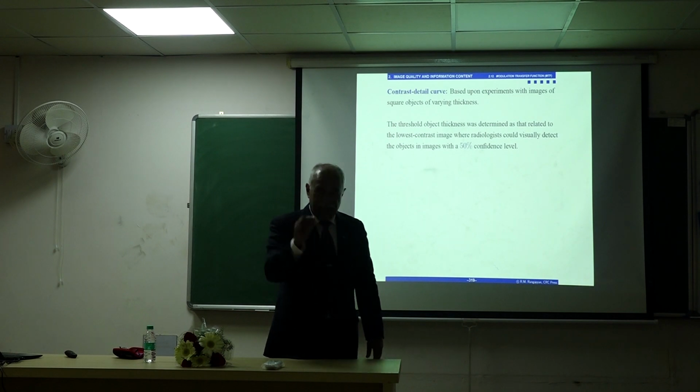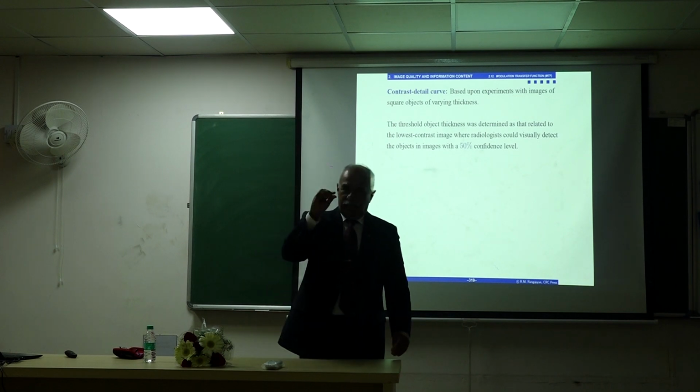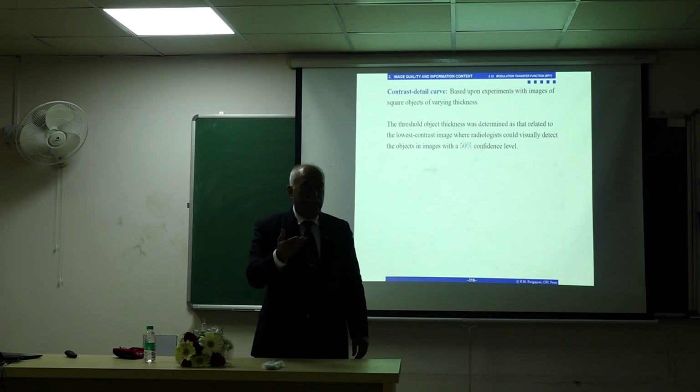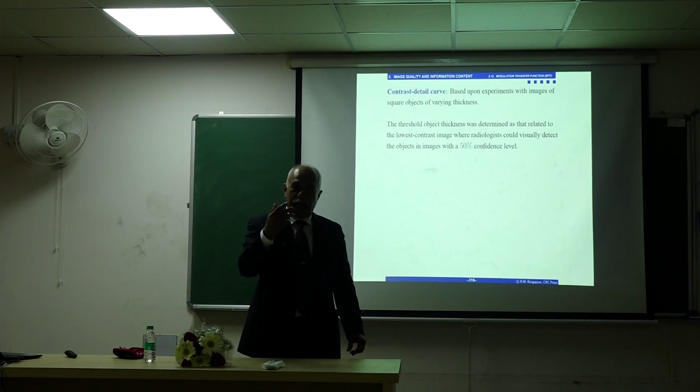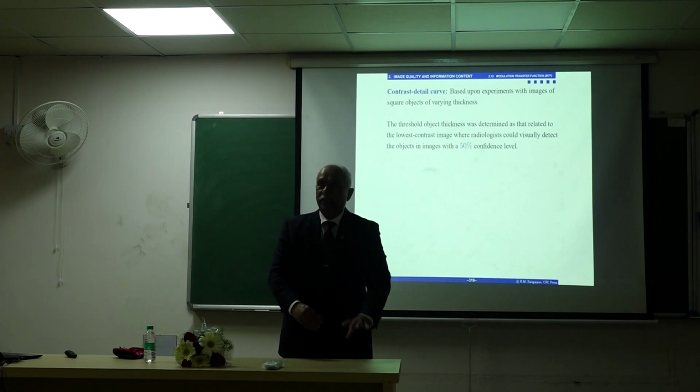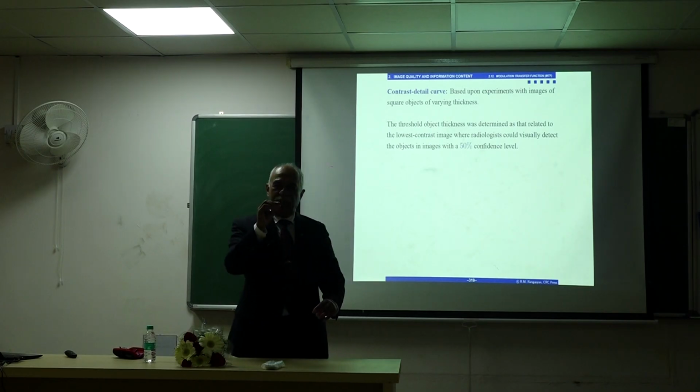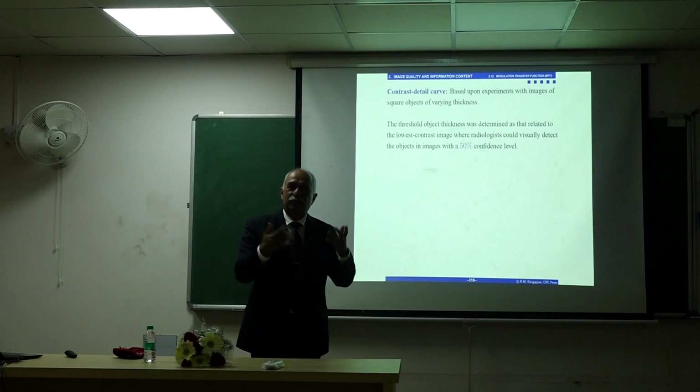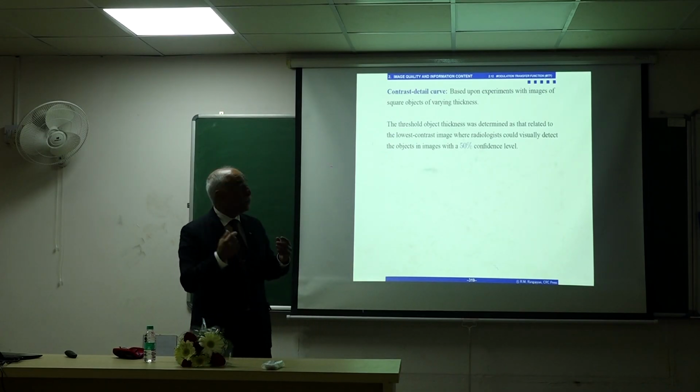If you just want contrast, just the thickness is varied. The thicker the material, the more the attenuation of the X-rays. And if it is very thick, there is more attenuation, so contrast is reduced. If it is very thin, X-rays pass through, you get higher contrast.